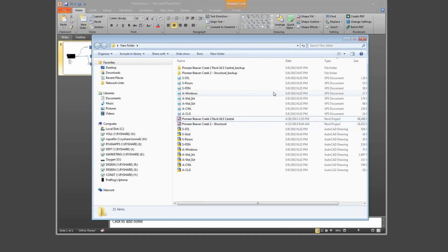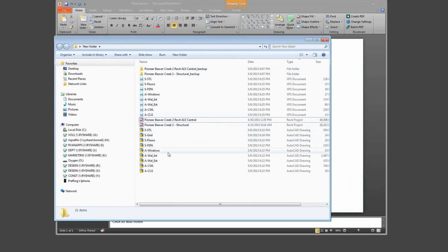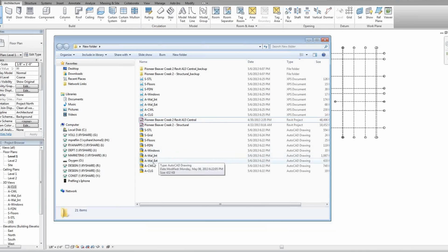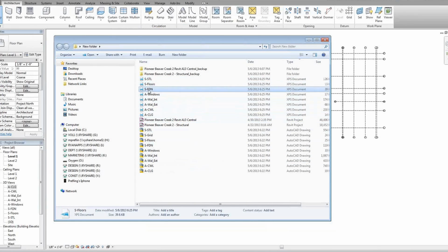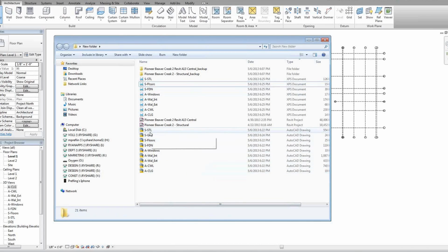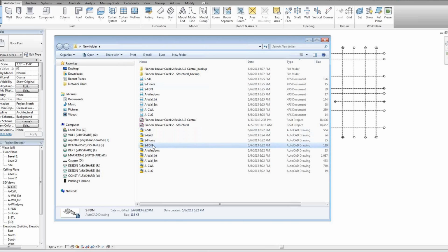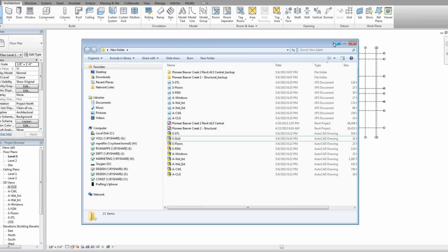So we've got a few more minutes. That's really the end of the Revit piece, which is how you isolate pieces of the models, and you're definitely going to want to export them all as pieces. You'll find the more you use Synchro, it's a lot easier to integrate the schedule when it's on pieces. Nicole and Jeff, I think you'll agree. And then the MEP guys will be extremely grateful that they don't have to load the whole freaking model to get to the underground, so that they can start their underground plumbing. They can just use a foundation model and a grid, and they can start underground. So it's the clean, efficient way to do things.